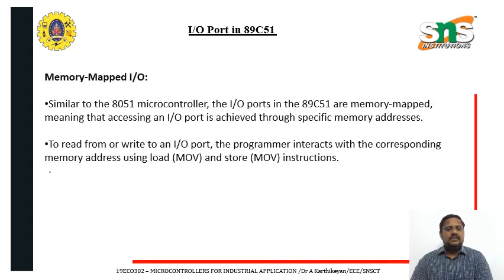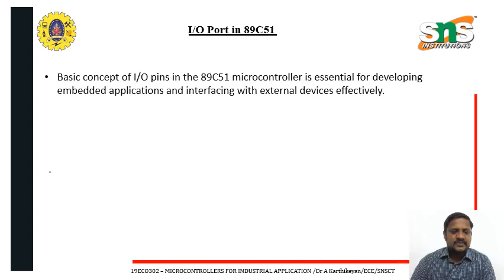Next is memory mapping of the I/O ports in the 8051 microcontroller. The I/O ports of the 8051 are memory mapped, meaning access to the I/O port is achieved through specific memory addresses. The program interacts with the corresponding memory addresses using load and store instructions, such as MOV. Based on that, it accesses the I/O port through the memory instruction set.